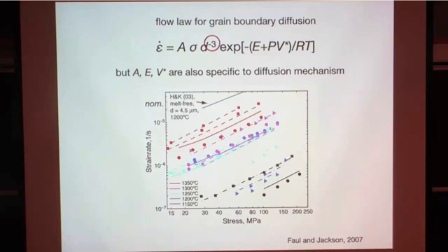But otherwise, yeah, log plot. This is log stress versus log strain rate. These are a whole bunch of experiments. You can see the temperature from 1150 to 1350. That gives you the temperature dependence. This is this E here, what we determine from the strain rate: if you fix yourself at a stress here and go up in temperature, the strain rate increases. So that's the temperature dependence here. As I said, we measure the grain size, we know the stress and so on.